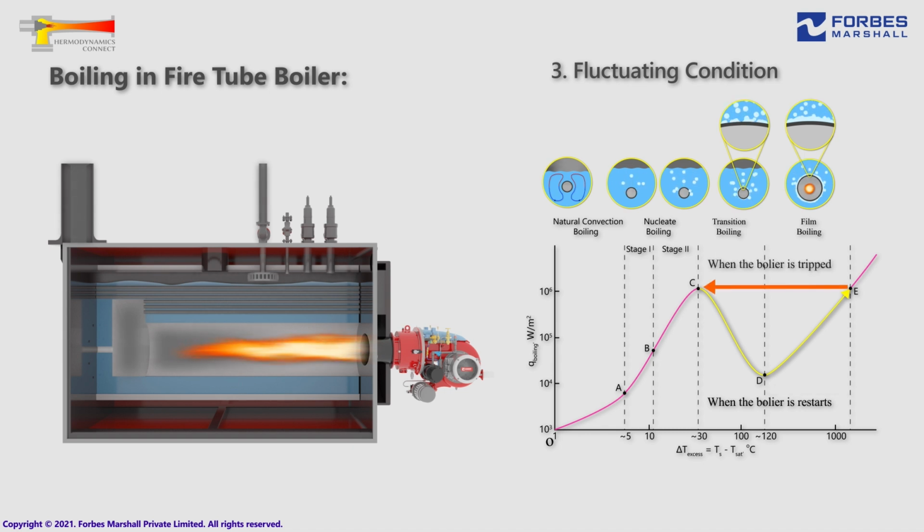Both these effects necessitate that the water level in the boiler as well as the safety cutoff pressure are carefully designed and controlled. This ensures that the boiler operates within the safety limit. Moreover, it also ensures that the stored steam above the water level inside the boiler is sufficient to adjust to the steam demand fluctuations as well as the resultant variation in the pool boiling phenomenon.